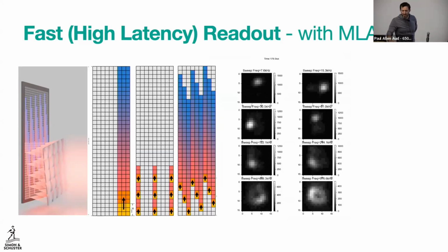And you're like, well, a micro lens array is a passive device, John. What are you talking about using it as a modulator? Let's start with an information theoretic question. If I want to have a 100 by 100 spatial light modulator for controlling a quantum repeater, and I want to be able to make decisions at 1 million frames per second for fast feedback, that's in the neighborhood of 10 gigabits per second of data that has to go through that device, right?